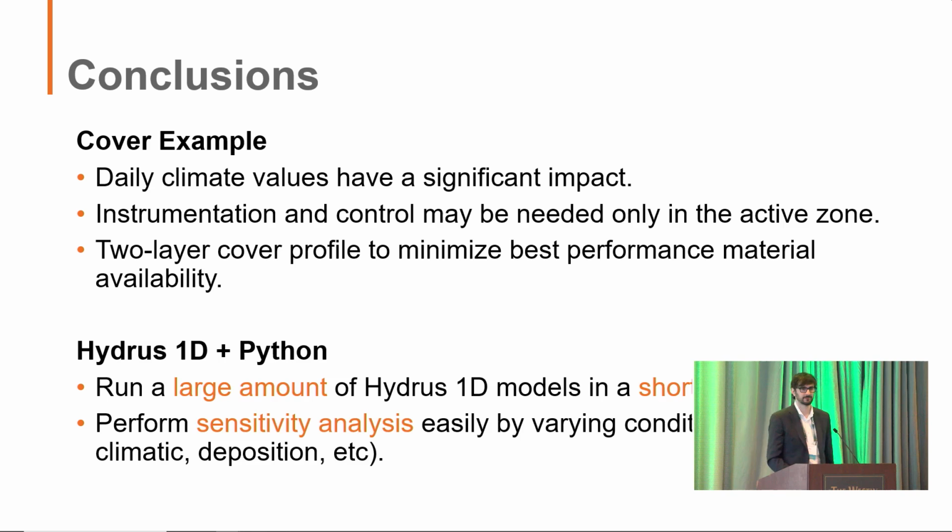I wonder if you used climate conditions for your boundary condition for the model, and did you have problems with convergence with Hydrus 1D? Or were you more in the steady state? Yes, we did. As I said before, we have a 40 years data set of climate conditions. We chose the mean one. And yes, we have to deal with some convergence issues, but we found the way to get it and get the results.